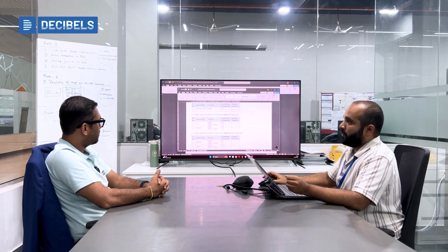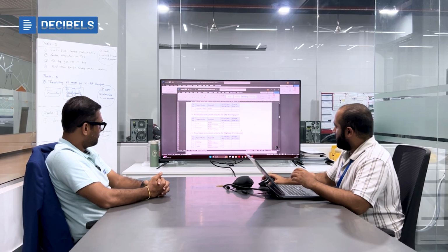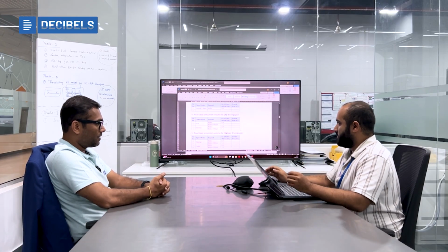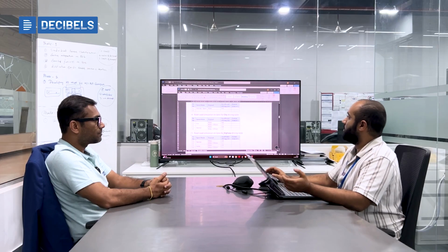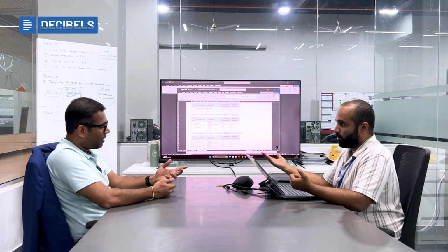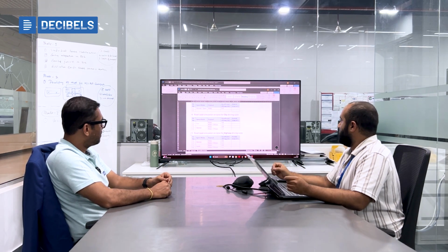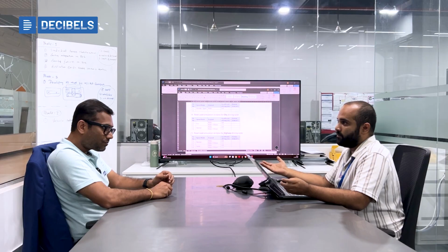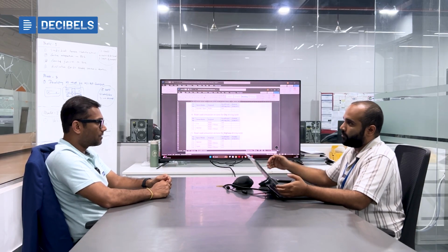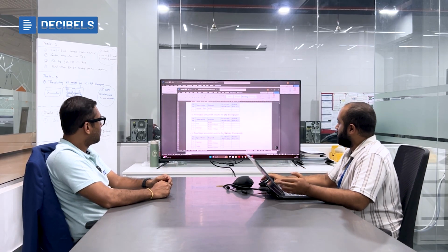So now I think these are the major tests that are specifically done. With these highway and city drive cycles, what we're trying to estimate is the range of the vehicle and the energy consumption, that is the watt-hour per kilometer. And how it will be affected in the highway condition with the pillion rider, and in the city condition with or without the pillion rider. So all these cases.